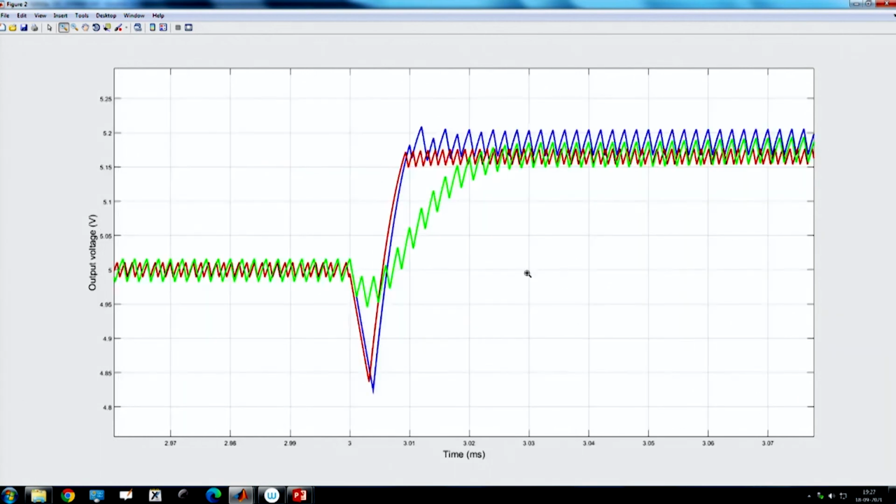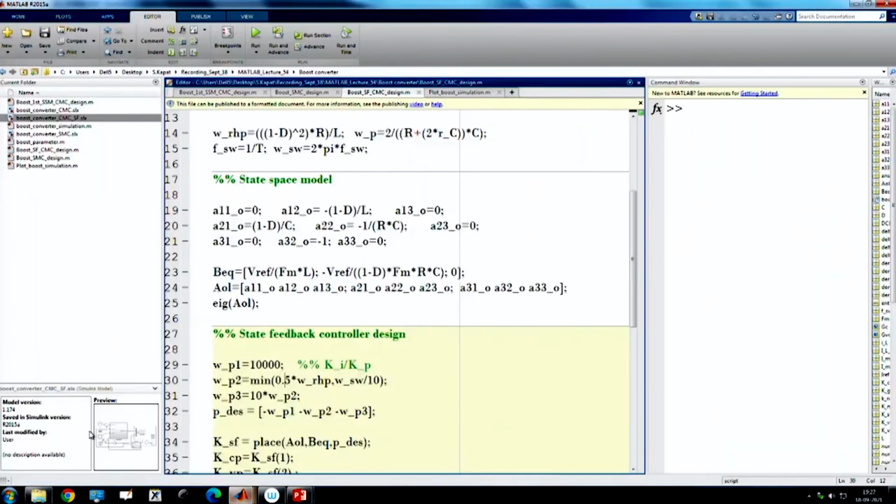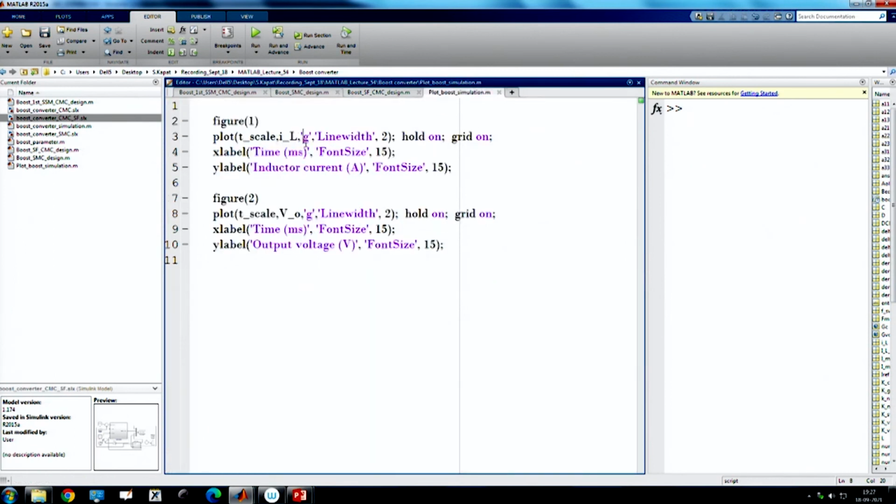of the RHP0. Now, since we have discussed large signal stability, if we go up to 1.05, that means we are going crossover frequency beyond RHP0, and our small signal model shows it is not simply possible. But using large signal Lyapunov stability, can we really achieve it or not? So, we are designing again using state feedback control to achieve a crossover frequency 1.05 times the RHP0, that means it is higher, and we are using a black color.